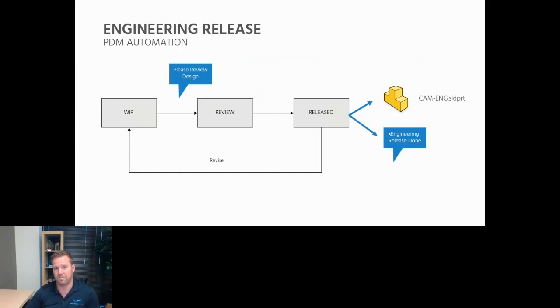You can also do other automation things like creating that CAM file. So SOLIDWORKS PDM Professional does have a full API. And so, those simple tasks, anything that you're doing repetitively over and over, I recommend looking into getting a script created for that. And you can instantiate those scripts or those tasks through different transitions. So in this case, when the file goes from review to a release state, it could automatically recognize files that, say, for example, had a built or purchase. If it was a built component, it would automatically create that CAM file doing that insert part into part feature. So you don't have a user having to manually do that.